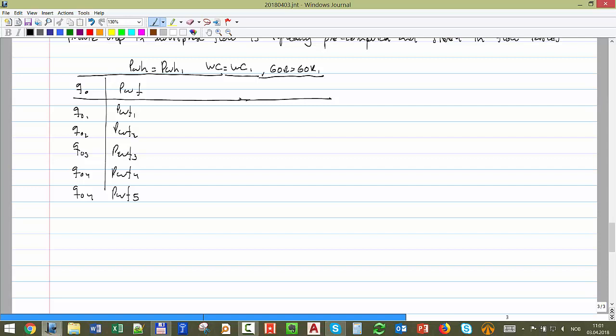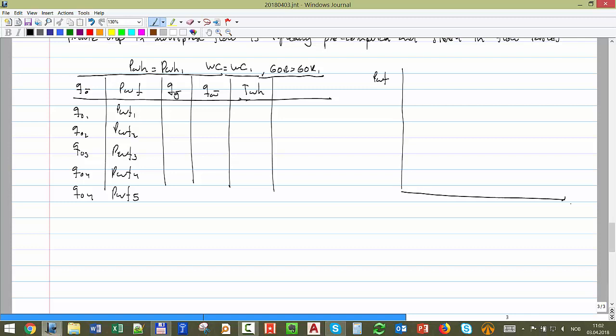Here of course I have oil at local conditions, and here I have Q gas, which is also reported, and here I have Q water, and also I might have the temperature of the wellhead, for all of these cases. But what this is going to give me essentially is Q oil, exactly those points in the curve. It's not going to give me that curve that I plotted before continuously, but it's going to give me several points in the curve.